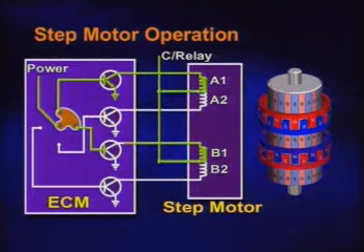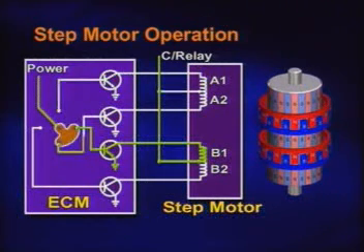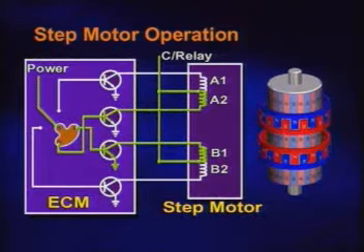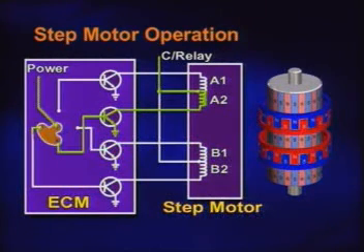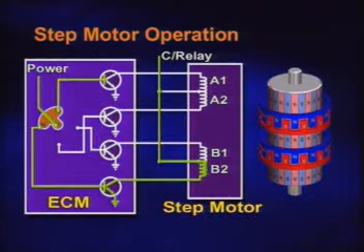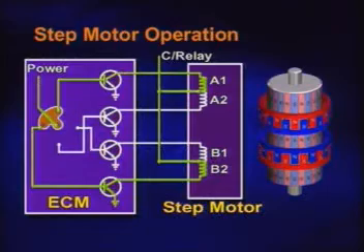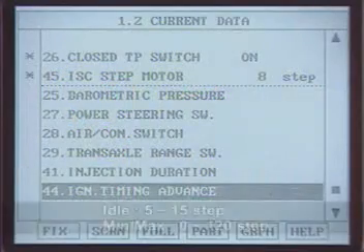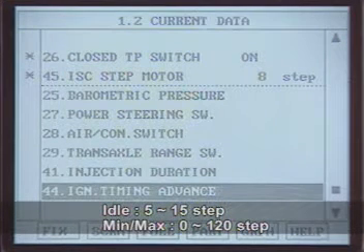Battery power is supplied to 2 terminals through the control relay. The others are connected to the ECM and 4 coils are controlled sequentially. The motor rotates by the on and off of the terminals in sequence. In reverse rotation, it is controlled in the reverse order. As for motor rotation, one rotation consists of 24 steps, and 5 rotations can be made because it has 120 steps.